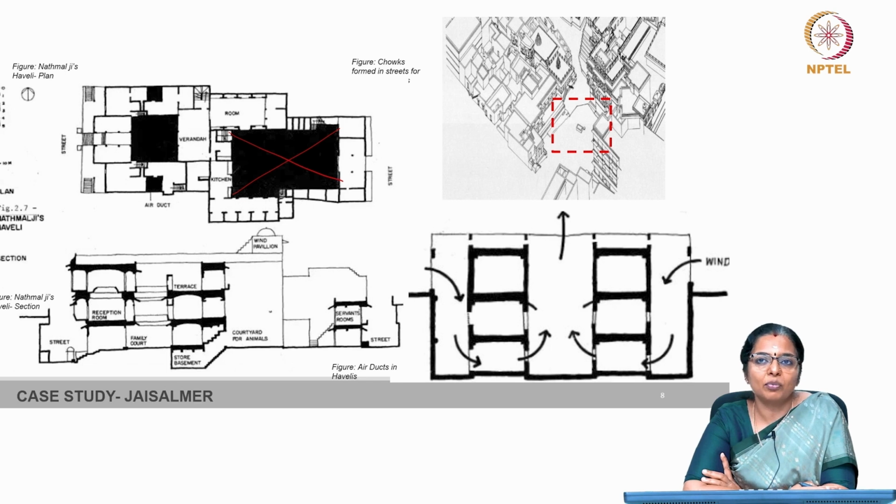This design approach significantly reduces heat flux into the building during summers. In winters, the lower altitude of the sun allows reasonable penetration. Wind gets deflected through the shafts, because there are some shafts too.